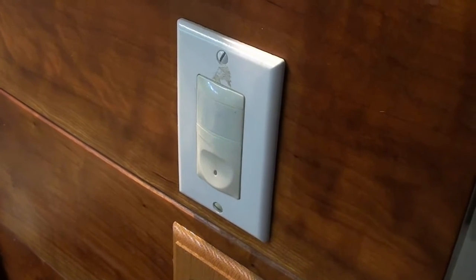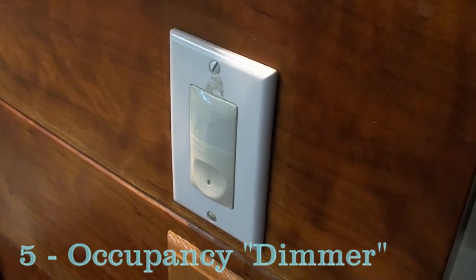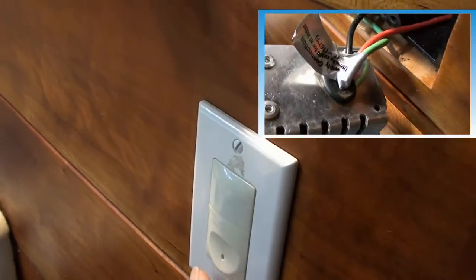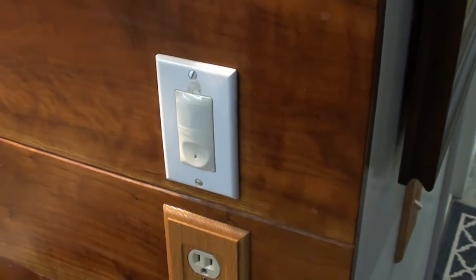This is an occupancy sensor, but it's one of the no neutral required solid state versions. And when this switch goes off, I've got a non-dimmable bulb in the fixture, and it starts this flicker problem. There's a couple of solutions. One is to put another bulb, or to use dimmable bulbs, and that solves it so that when it comes on. But you're still losing that 5% of brightness by using this particular fixture because it's switching through the triac.